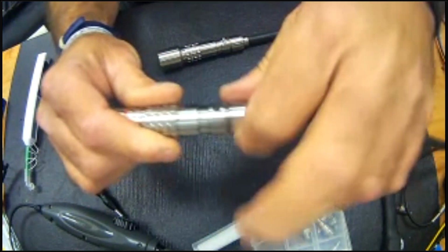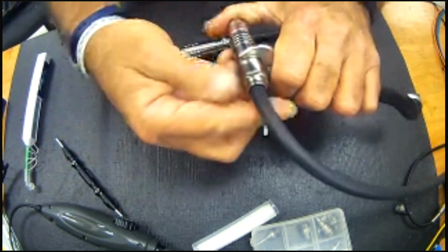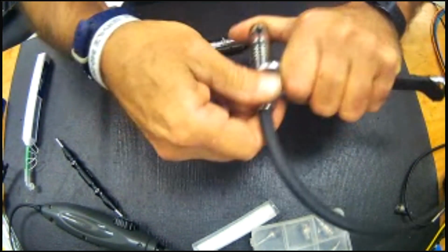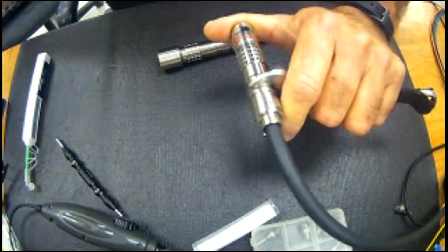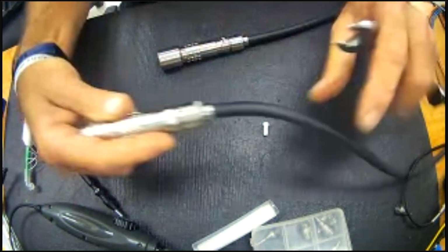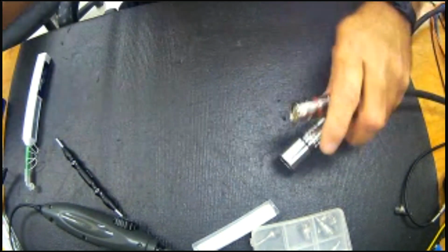and then you would bring the back nut up, a couple of pounds of torque there, and it will be required that you hold the first one to tighten the second one. And then, again, the same thing. 15 millimeter, very, very thin wrenches. Tight, you are done. That is all it's taken to assemble and disassemble one of those.